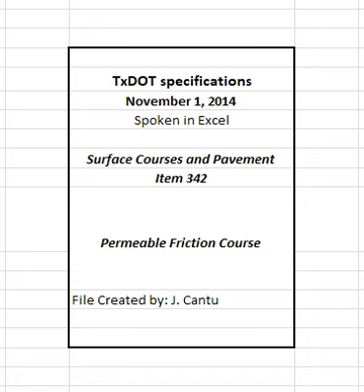4.9.7 Ride quality. Measure ride quality in accordance with Item 585, Ride Quality for Pavement Surfaces, unless otherwise shown on the plans. 5. Measurement. PFC will be measured by the ton of composite PFC. The composite PFC is defined as the asphalt, aggregate, and additives. The weights of asphalt and aggregate will be calculated based on the measured weight of PFC and the target percentage of asphalt and aggregate. Measure the weight on scales in accordance with Item 520, Weighing and Measuring Equipment.